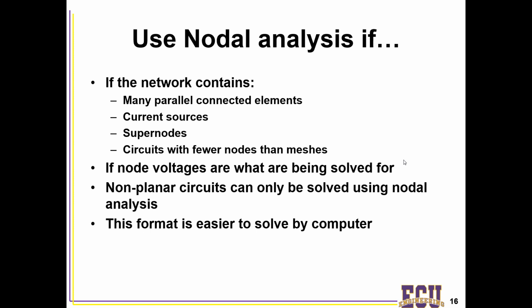If you happen to have current sources, nodal analysis makes it really easy. And of course, if you have supernodes, that is, if you have a voltage source that happens to be between two different non-reference nodes, then that makes it a lot easier to do nodal analysis rather than mesh analysis.